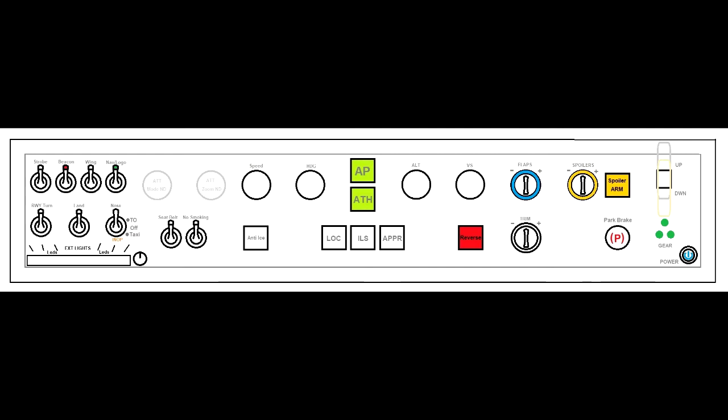Behind this power supply I have a fuse box with a typical 12 volt fuse you can find in cars. I thought that it was very sufficient because with all LEDs illuminated, the circuit will not use more than 0.55 ampere. The size of this box is 10 by 50 centimeters, which takes less place on the desk than a square-shaped button box. I didn't make a detailed plan with measurements.